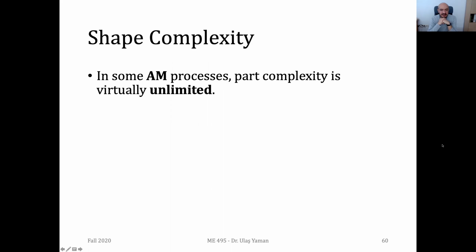Yes, actually, FDM and powder-based systems have more unlimited complexities, but to me, powder-based systems have the highest part complexity. Think about some assemblies, moving parts: you can try to print them on FDM or FFF, but you need to have support structures.